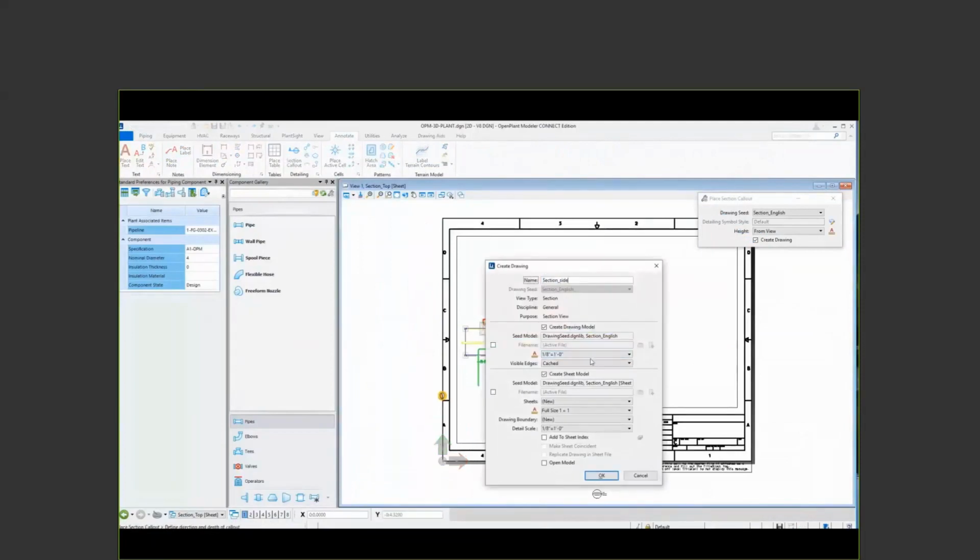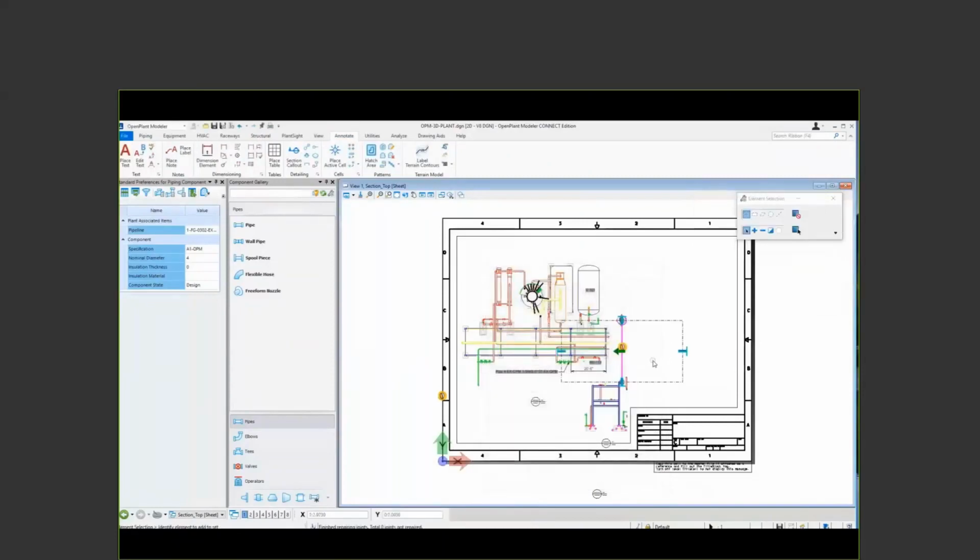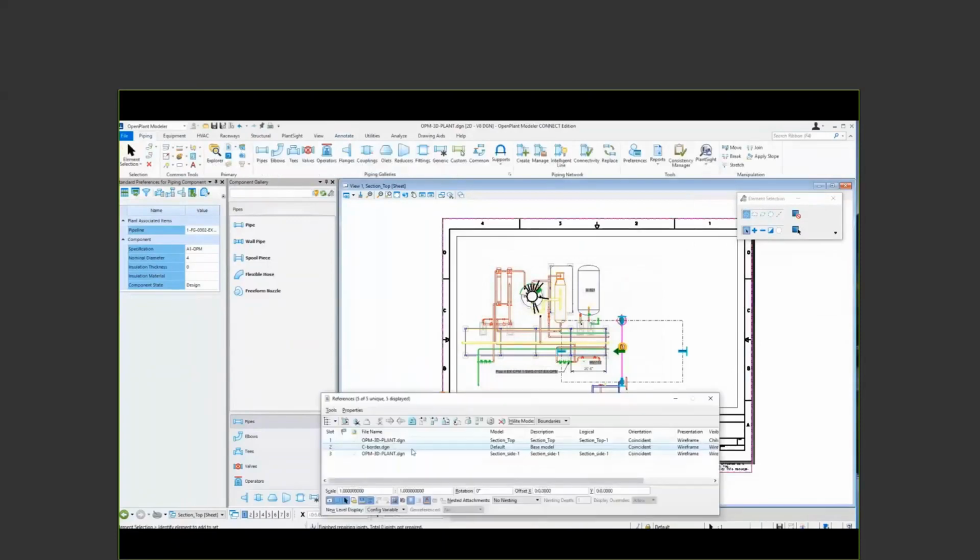And this is what we call a dynamic view. We'll place this on this particular sheet that I'm on. And any scale factors we need, I'm going to turn dynamic on, so it dynamically updates as we change our clipping planes. And it inserts it in the drawing. At this point, it's just a regular reference, so I can move that reference to where I need it in my drawing.